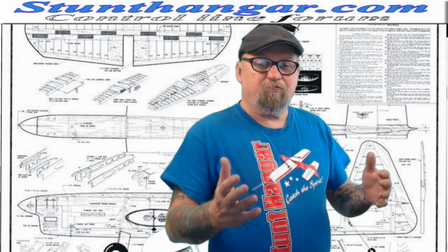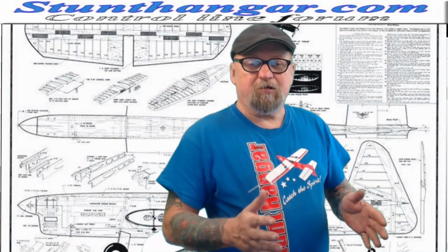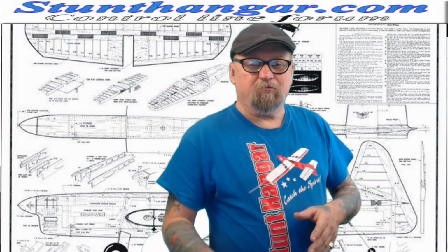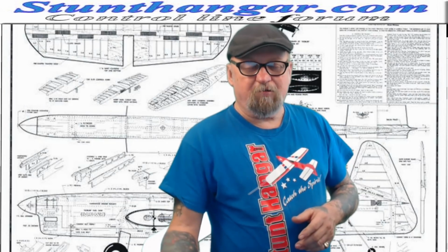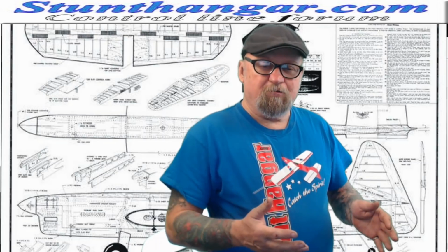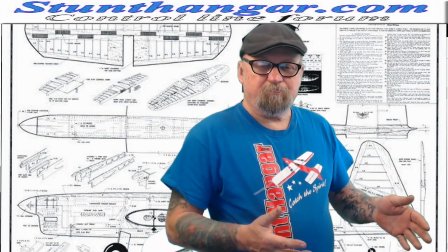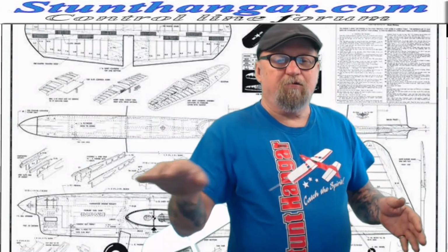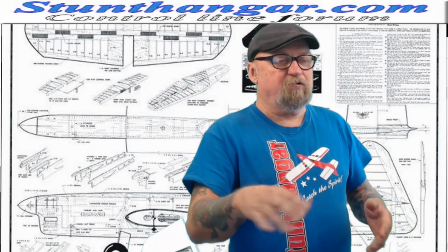The nose shifts forward because the greatest percentage of the weight is behind the CG, so the higher the weight goes, the more tail heavy it is. So you can either build it lighter or lengthen the nose. If you lengthen the nose, we're back into that clock time thing where you're flying along and it takes forever to go around the corner.